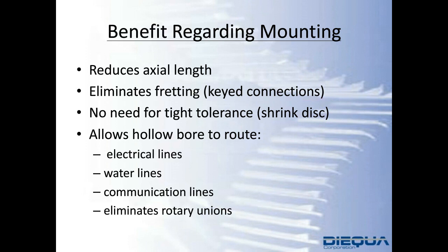For example, a hollow bore might be an H7 fit, but the shaft would have to be a J6 to minimize the distance that the shaft has to collapse down onto in order to have that positive connection. Whereas with a robot flange, you have your standardized dimensions, and everything would then be piloted off of the face.